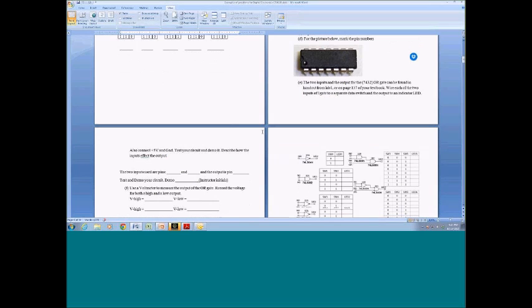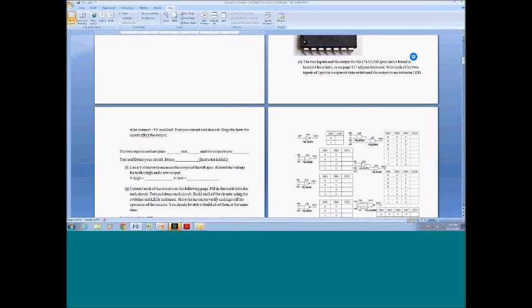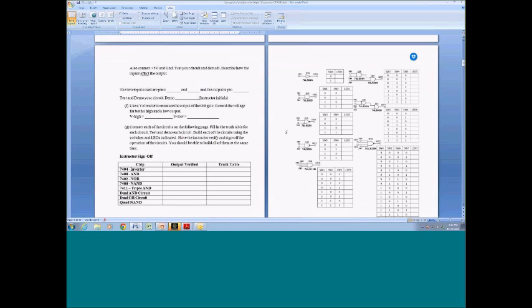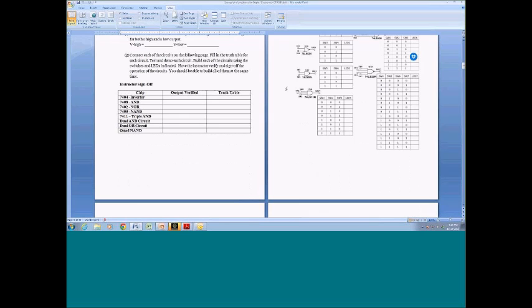So they go through and they'll use the example, for instance, of an OR gate, and then they wire it up. I have them note down what the pins are. They have to demo it to me. I go through and sign off on everything, make sure they have it down, and then they have to build each one of the circuits on this side. They have to do the truth table, and they have to verify that it's fine. And this is how they learn all the gates. They get a little confused when they do multiple gates like this. They don't realize the output of one is the input for the second one, and there are 2 gates on the chip. But this is what this drives home. Okay, so this really is the first part of that.